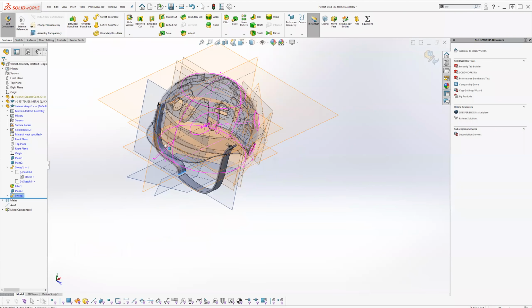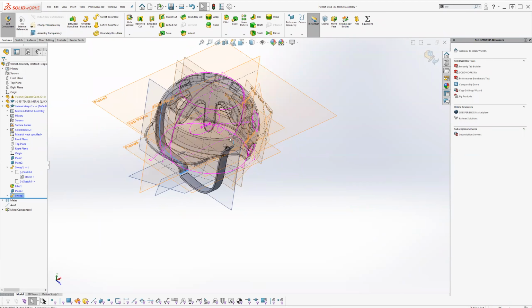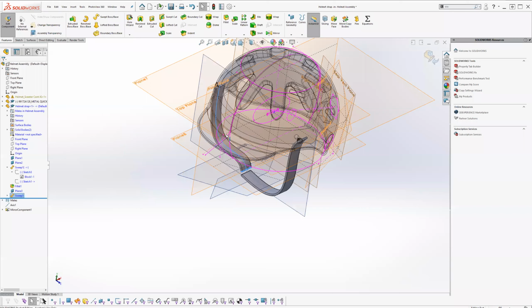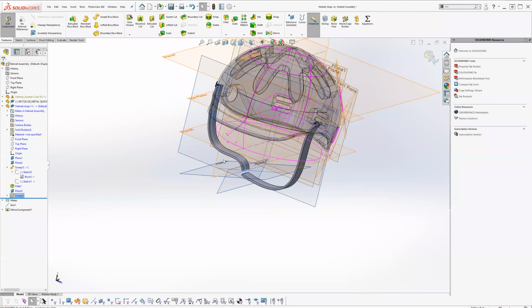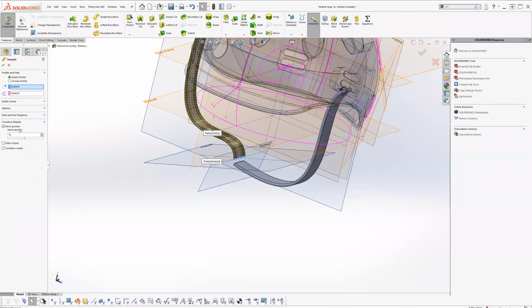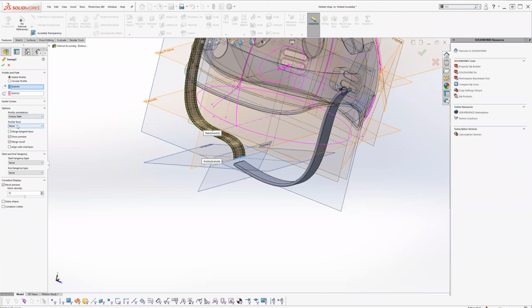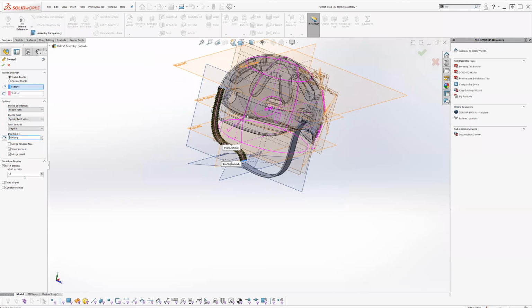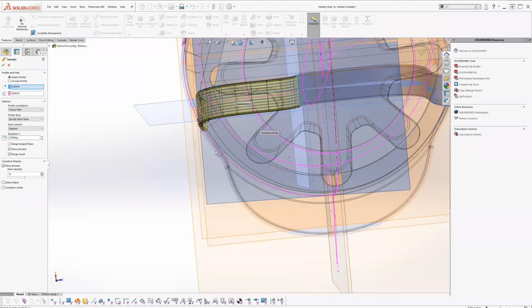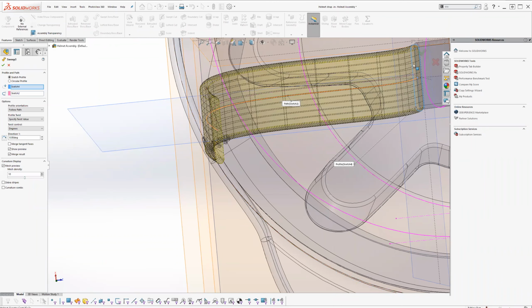So right now this looks kind of rigid because it's a 2D sketch, but you can do a 3D sketch to make it a little more flowing, or however you want to do it. But even just by having a spline, it's kind of flowing already. One thing about the sweep too is that you can add a twist to it if you need to. If you go to options, see it has this profile twist. You can specify a twist value. Let's say where it ends, see how it's not quite parallel to the originating profile. You want it a little bit more twisted at the end.